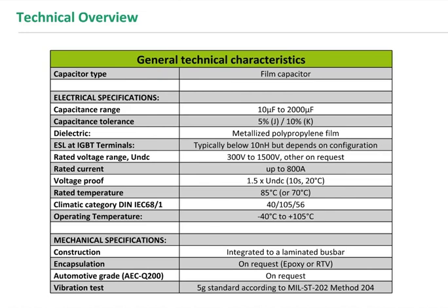There are as well the DC capacitors, and there are internal IGBTs, but also different types of connection, specifically between the IGBTs and the busbars. So we have this expertise in creating this module in a low inductive way.